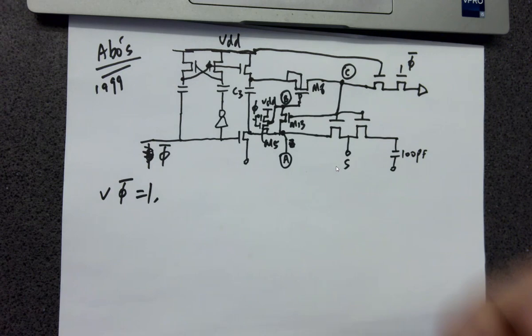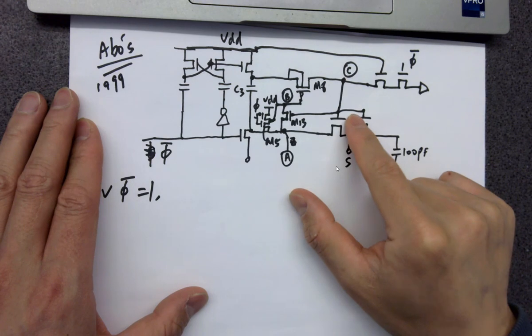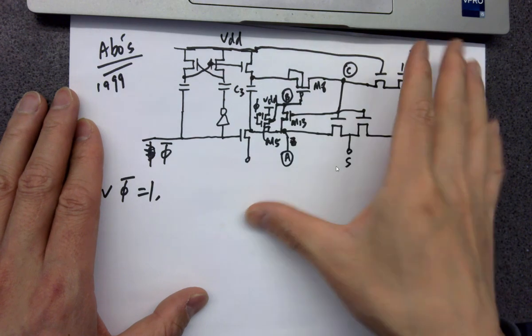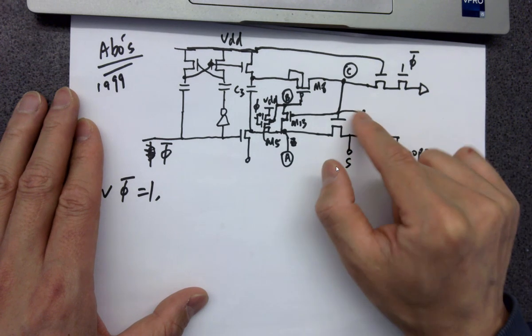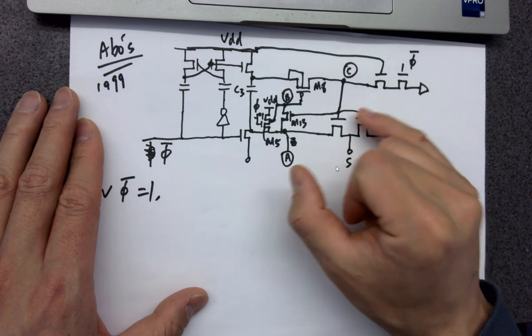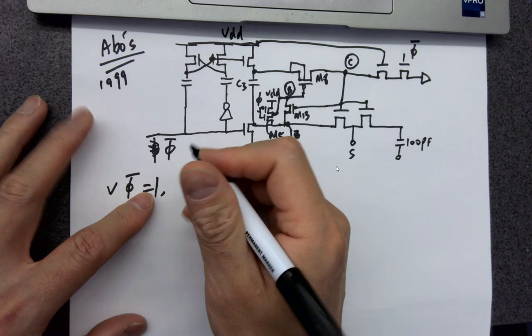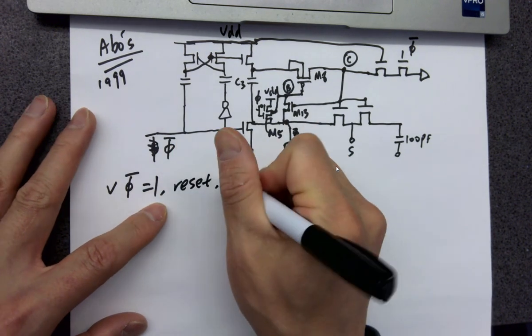So in that case, you do have the time to reset everything. It's passing the 0 here. So whatever was previously stored over here, the charges across the gate will be reset by the 0, discharged to the 0. Or you can say the 0 is going to reset all the voltages of the gate. So when phi naught is 1, what's happening? It's resetting and it's holding, right?